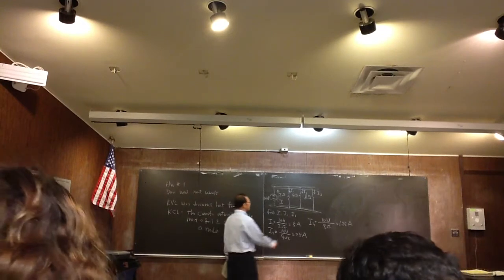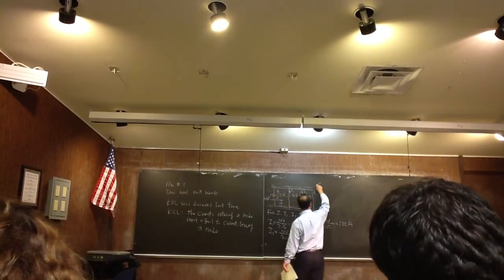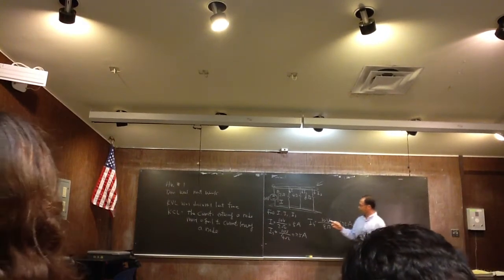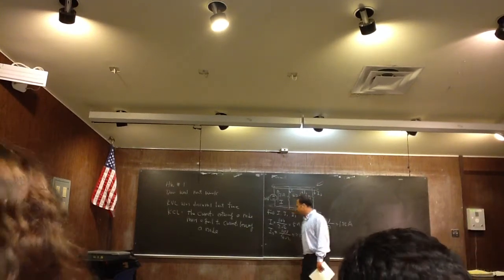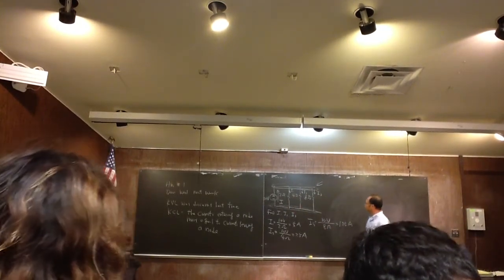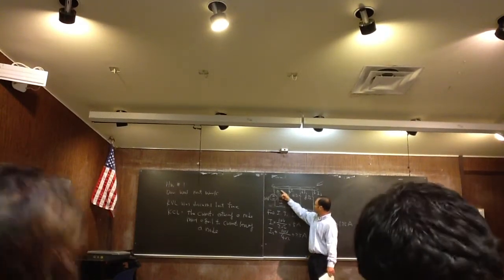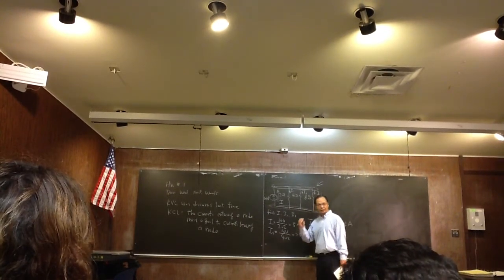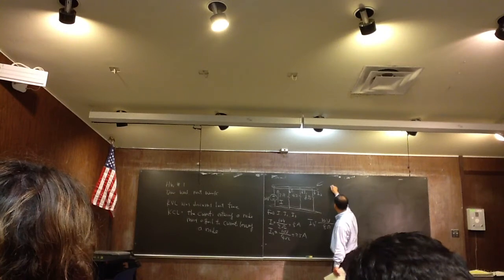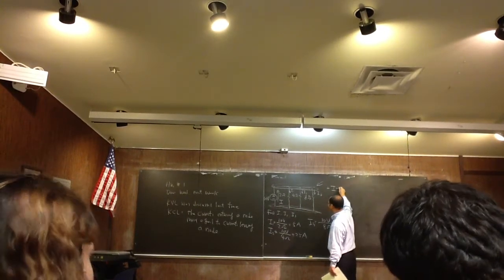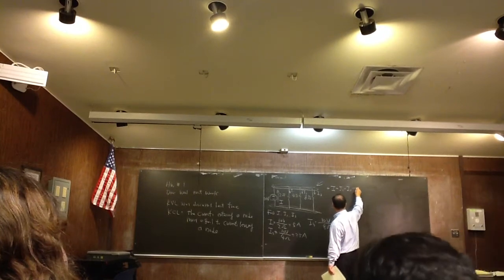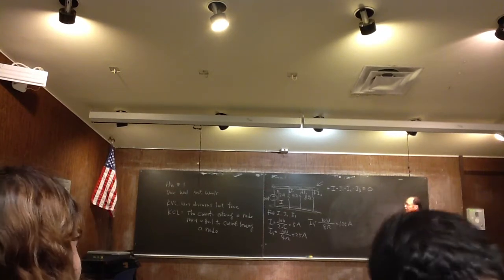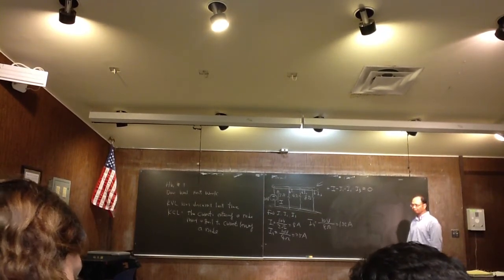So if you look at this single node right here, I can apply the KCL. KCL says the currents entering and leaving must be equal to each other. So what you can do is say the current entering the node is positive, and the currents leaving the node are negative. Therefore, I minus I1 minus I2 minus I3 must equal 0. So that is basically the KCL.